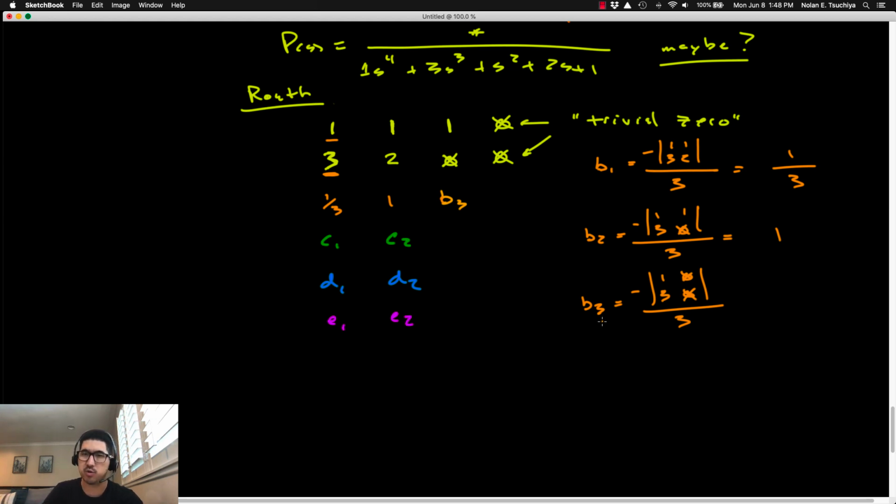That's a special rule that I've made up about doing the Routh table so that you don't get confused. And when you get a trivial 0 for one of the values, like B3, that's an indication to move to the next row. So that row is done. The minute you get a value of trivial 0 in a row, that means to start a new row. That's the application of this trivial 0 idea.